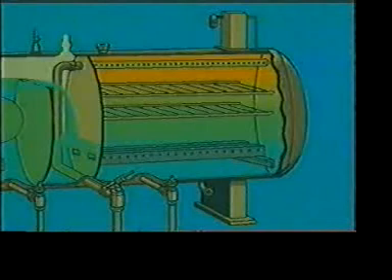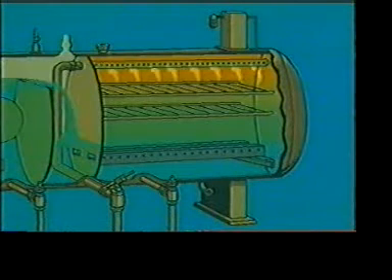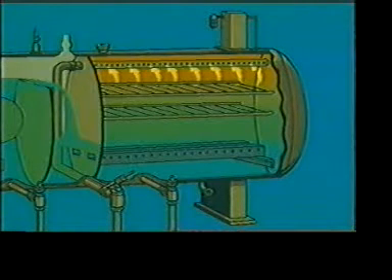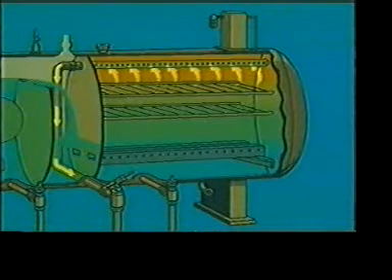As the heated emulsion rises through the electrostatic field, water droplets are given an electrical charge which elongates and polarizes them. The alternating current causes the water droplets to rapidly move around and collide into each other with enough force to break the film surrounding each droplet. The water droplets combine into larger drops and settle to the bottom of the treating section for removal through the treated water outlet. The oil, which has separated from the water, then rises to the top of the treating section. There, a clean oil collection header skims off the clean oil for removal from the treater.